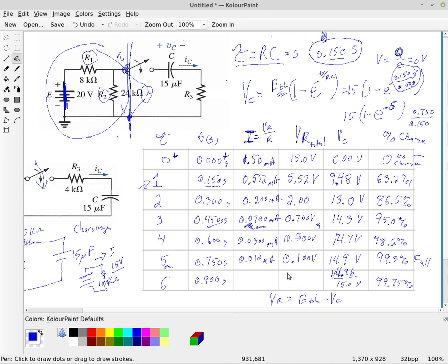If we look at the true actual voltage out to about 5 digits, that would leave VR at about 0.0372 volts. So it's close to zero, but it's not quite zero. And then of course our current would be 372 microamperes if we move our decimal place.